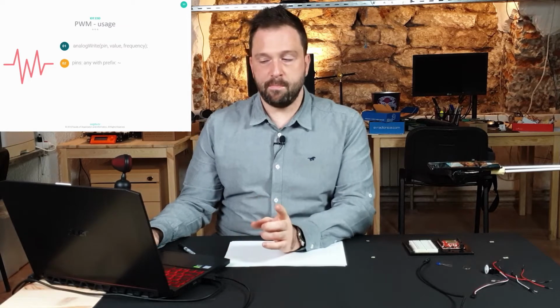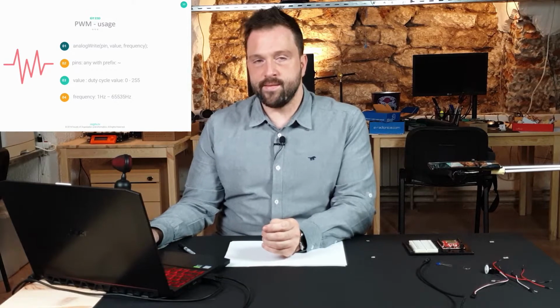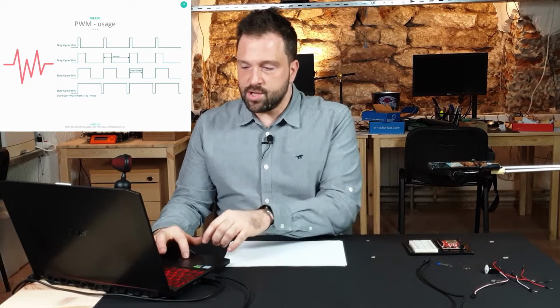parameters. Pin, which can be any pin that has a prefix tilde, and value. It's a single byte, meaning that it's an integer number between 0 and 255, and frequency between 1 Hz to 65,535 Hz. And in this slide, you can actually see what a PWM is.